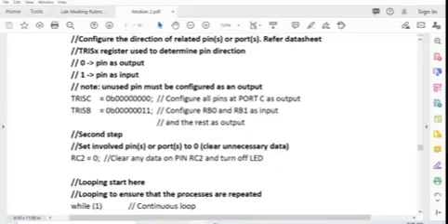You can only do this type of configuration provided that the pins are free. You are using only pin RC2, and the rest is free. You are not connecting the available pins to the rest of the load. It can be either LEDs or switches.